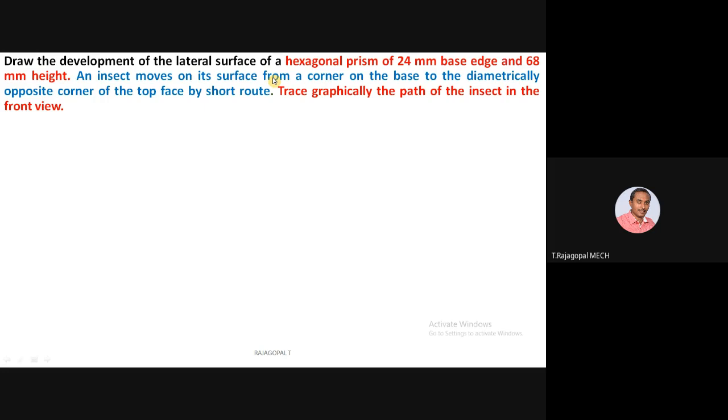Being a hexagon, you have to draw the position of the hexagon correctly. Also, whether the top view is a hexagon or the front view is a hexagon is never straight away given in your question. Second point, even the position, they never mention what the position of the hexagon is. Then third is the section plane; there is no section plane condition here. So this is an interesting question. If you have that capability, try and tell me what the top and front views are first, where you will draw the hexagon, top view or front view.